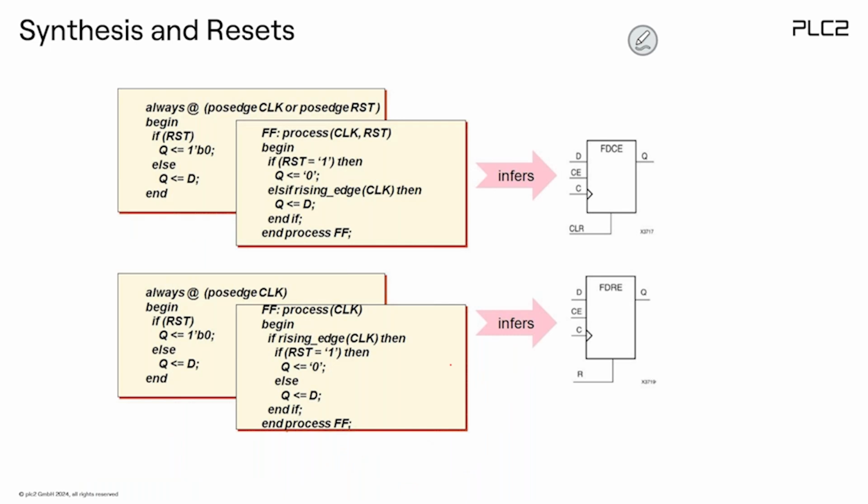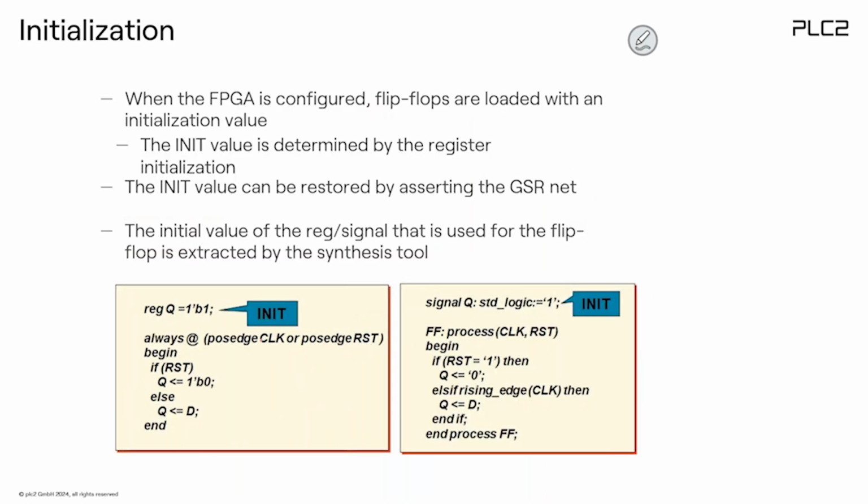So this is basically the definition of the reset in Verilog and in VHDL. That would be Verilog, and that would be VHDL. That's Verilog, that's VHDL here, and this would be the asynchronous reset, because we are asking reset first, and that would be the synchronous reset because we are asking the clock first. That's how we actually describe the different kinds of flip-flops.